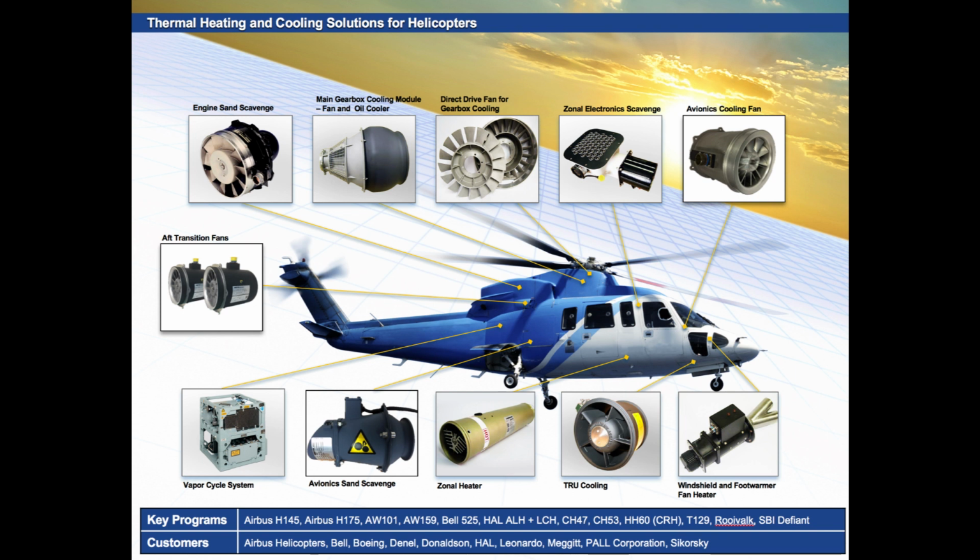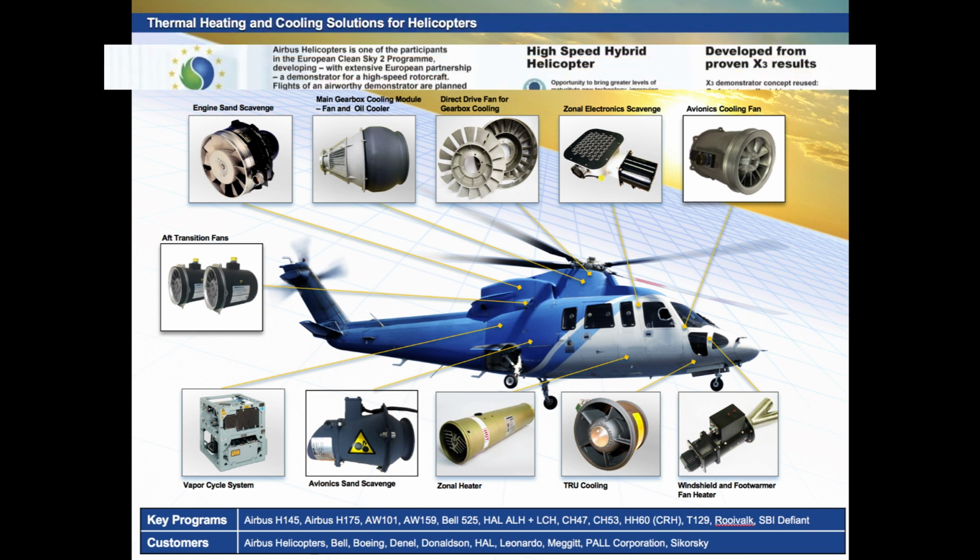One of the simplest methods of cooling a helicopter is to remove the doors, allowing air to flow through the cockpit and engine compartments. Care must be taken to store the doors properly, whether in a designed door holding rack in a hangar, or if it is necessary to carry them on the flight, in the helicopter. When storing the doors, care must be taken to not scratch the windows.